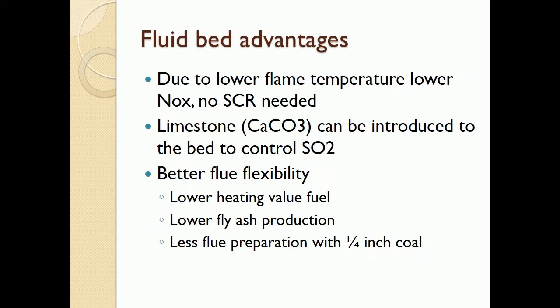Fluid bed boilers have these advantages. Due to lower flame temperature, lower NOx, no SCR needed. Limestone (CaCO3) can be introduced to the bed to control sulfur dioxide. Better fuel flexibility. Lower heating value fuel. Lower fly ash production, and less coal preparation with 1/4 inch coal.